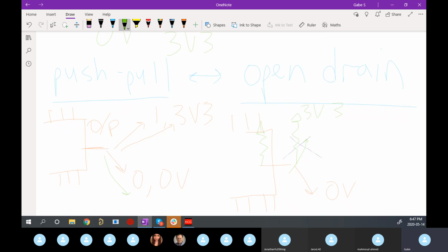If you think about it, if I have control over my line, let's say that's a signal. I'm outputting a signal that is a fault state. Let's say I just had push-pull. I want to define it as 5 volts, or sorry, 5 volts or 3.3 volts. Everything is good. My logic 1, that's fine. Or 0 volts. Everything's bad. Sound the alarms. Everything's on fire.